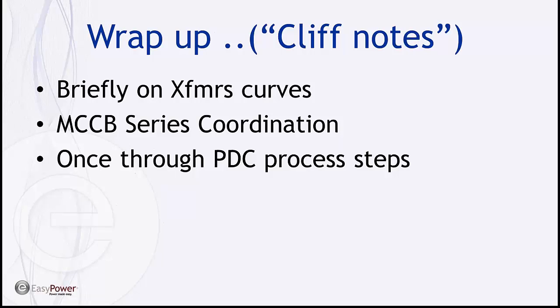So today we're going to wrap up with a Cliff Notes version, very briefly touch on more in-depth information on the transformer curves, which we promised earlier and didn't get to, and then address briefly the series coordination capabilities in molded case circuit breakers, and then finally do a once through the PDC, the protective device coordination process in kind of big picture steps, and see if we can address some questions after that.